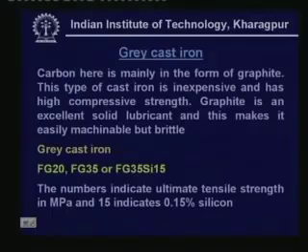Normally you find the yield point, then the material goes to an ultimate stress value, the maximum value, and then it ruptures, or it fails, after the breaking point comes. In that way the maximum amount of stress that the material can take up is the ultimate tensile stress, and that is in MPa.